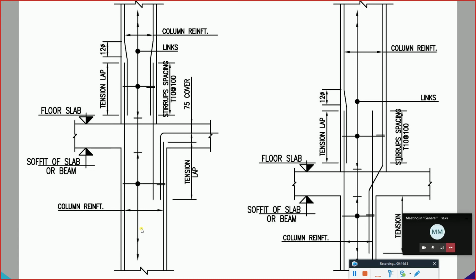If we have different cross section, then I need to ensure that every case is covered, whether it's the same edge of the other column, so we are having one straight like the regular condition. If it's ending up with a roof, it's not going for the column directly, then we should go and put a connection reinforcement. And then the other area where the top column is ending, then we need to make one new reinforcement for the bottom column.